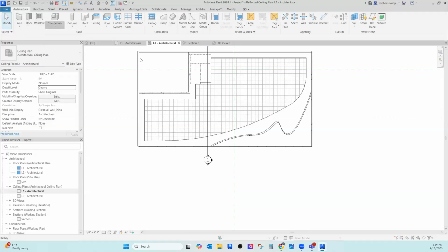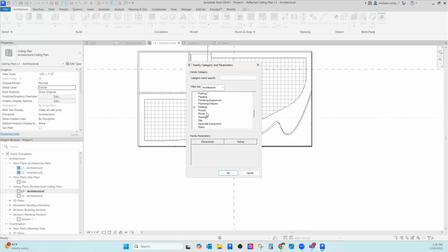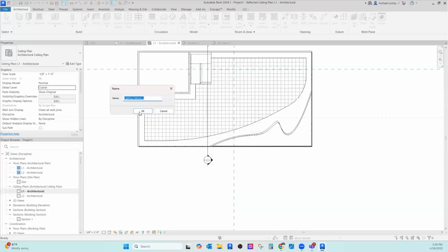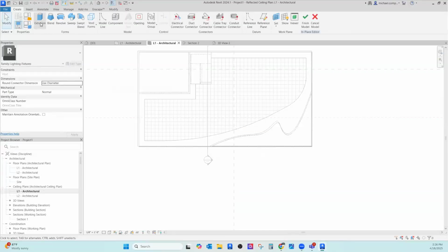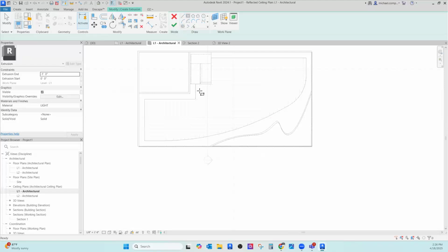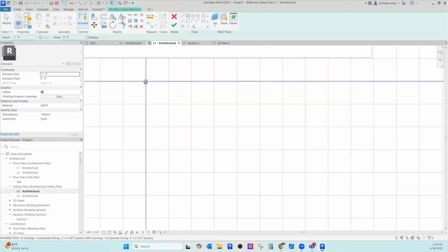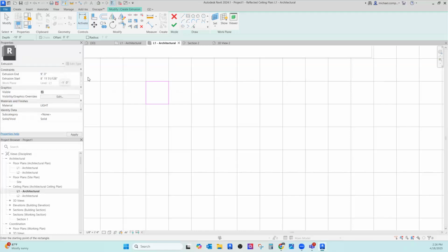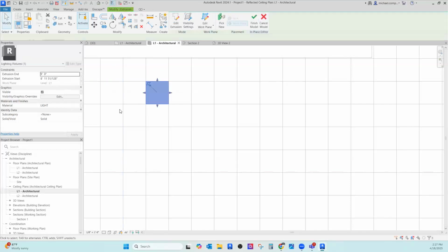So we're going to do lights again. And this honestly is what I do. You can download lights from lighting manufacturers, but they're so complicated to use, and I just need a simple rendering. This is often what I do. So by default, I will put these at 8.95 feet, ending at 9 feet, right? And then it's already the light material.